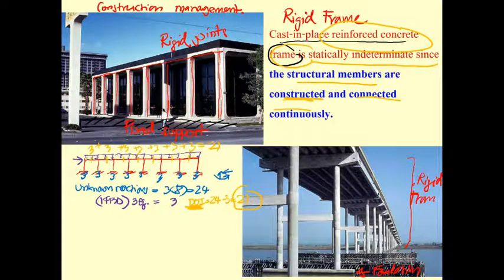During construction, the contractor will start by building the piles and casting the foundation to cap the piles here, and then they construct. They may place the reinforcement and the formwork, and cast the concrete into this column, and two of them are supposed to be built simultaneously, up until here, and then you build a cross beam.